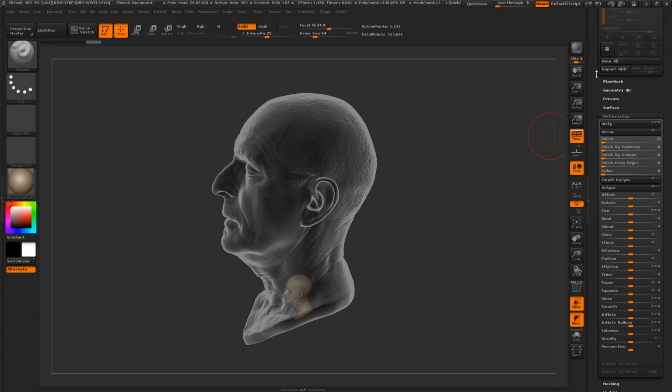So you bake with the eyes closed, blend shape layer on. It depends on the process that we're using and the final results that we want for the specific character, if we would bake with the eye closed blend shape on. I personally haven't done any baking with the eyes closed simply because I haven't needed to. Also, since the blend shapes don't actually affect UVs, it's just not something that I'm really going to have to worry about most of the time, because no matter what, whether I have the blend shape or not, I'm still going to have the same resolution in the UVs.